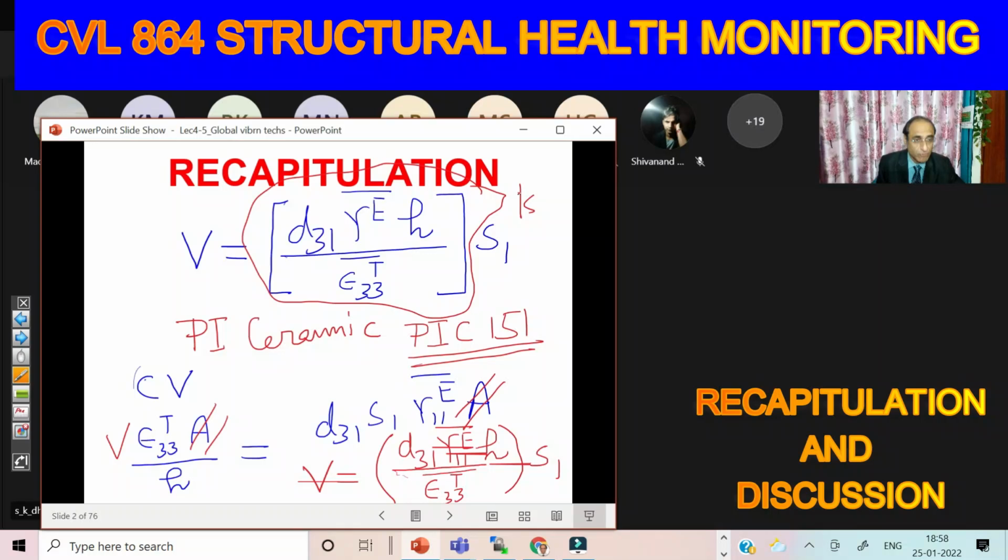So what you are getting from the experiment is the voltage output. You will see plots like this, the way Madhu has done the experiments. All you have to do is find out the voltage, and just like we used the conversion factor for the accelerometer, use this conversion factor to obtain the actual strain. Alright, so any doubt till now?